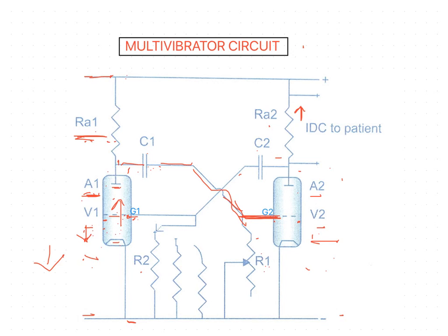C2 therefore begins to discharge through R2 and V2, and its left hand plate gradually loses its negative charge. The grid of V1 is connected to this plate with no resistance between, so it is at the same potential as the condenser plate. Thus, as the condenser discharges, G1 also loses its negative charge, and when the charge falls to a certain level, V1 again begins to transmit current.